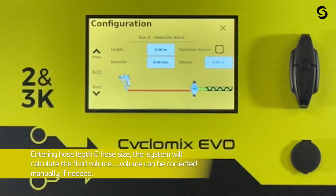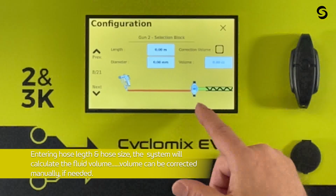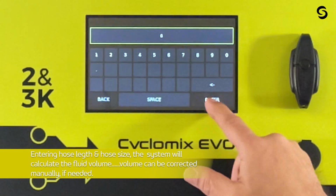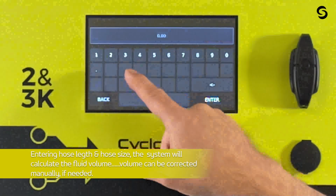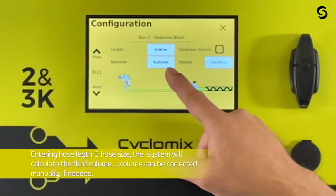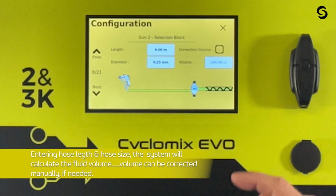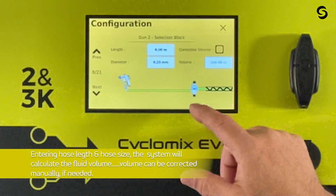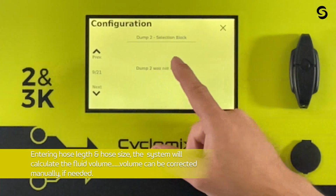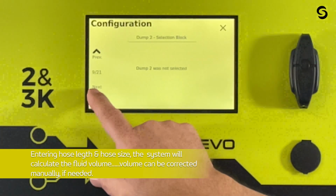Now we're going to gun 2. Gun 2, we did not set up a dump, so we have to set the hose length here from the 2-gun management valve to the gun. This one we're going to say is 6 meters, and we'll use the same 1/4 inch or 6.25 millimeters for ID of the hose. And you see the value here is calculated out. And again, if I needed to adjust that, I can just select the correct volume. Now, I didn't select a dump for gun 2, so it does not show up here in the configuration.